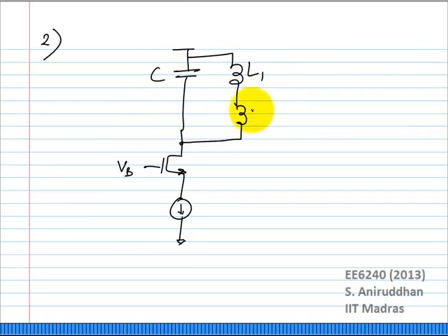C, L1, L2, and I'm going to take the tap between the two inductors and feed it back. Obviously this looks slightly different because of biasing details, right? Because I need the DC current to pass through the inductor, so the inductor actually has to be connected to VDD, unlike the capacitor which could just be connected to ground. But it's basically the same circuit, right?